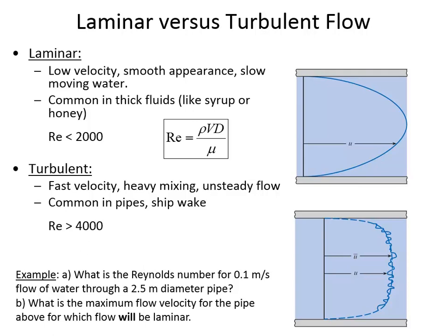Well, since it was laminar before I got into the transition zone, it will stay laminar unless I increase the velocity even more above the point at which it transitions at a Reynolds number of 4,000. Or if it was in the transition zone and I hit the pipe with a hammer, I would have forced a disturbance, like a little shock wave that would induce turbulence, and then it would be turbulent.